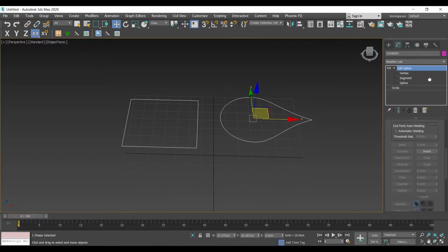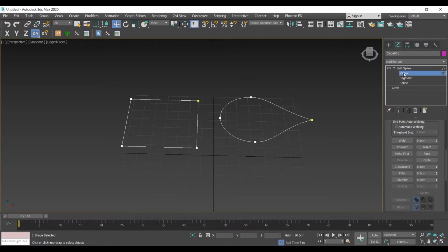Now, if you go down, you see that I have a lot of things in here grayed out. In Edit Poly, we used to select Vertex, and then we have a new tab called Edit Edges or Edit Vertices. If I go to Edges, I have Edit Edges. If I go to Polygon, I have Edit Polygons. And each one of those has its own tools.